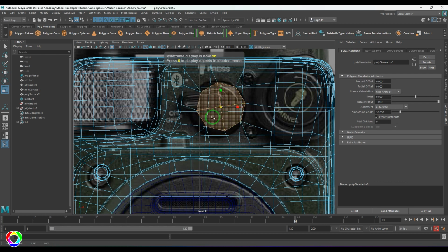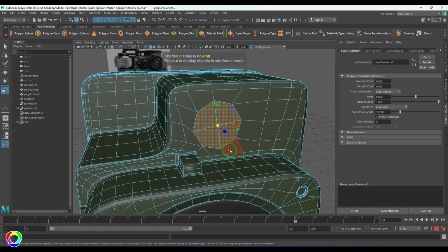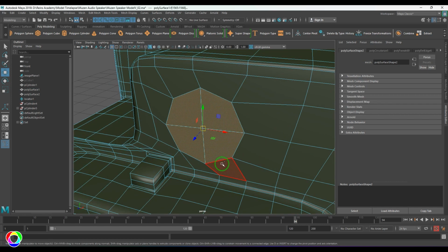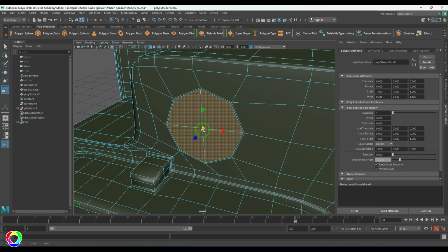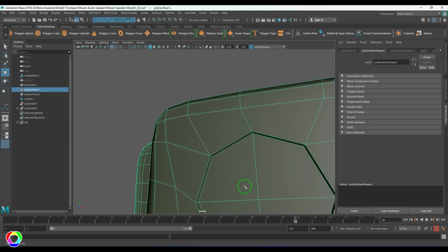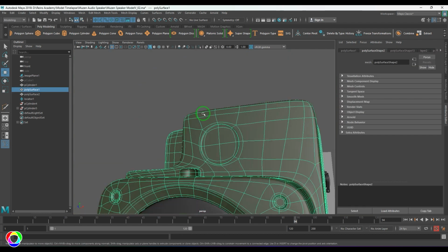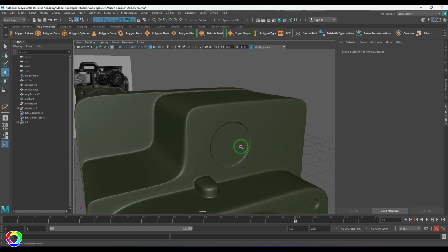And then I'm going to scale this and move it there like that. If possible, I can rotate and then relax the lines there. Press Ctrl E to extrude and then just slightly scale and move it inside. And add 2 lines there to get that nice ridge.